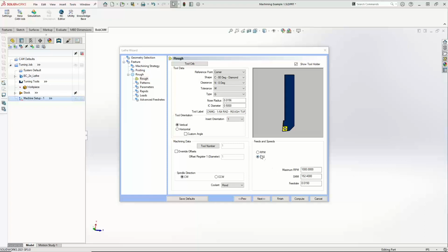All right, good. All right, so I'll leave it. I'm just going to go with RPM mode. We'll do our maximum RPM, and then I'll say my spindle RPM is just 500. So, yeah, we'll try it that way. Feed rate should be the same. Feed rate's 15,000. That's why I kind of know that there's something wrong here, because the 15,000 is staying the same, which is very odd. I'll have to report that one.